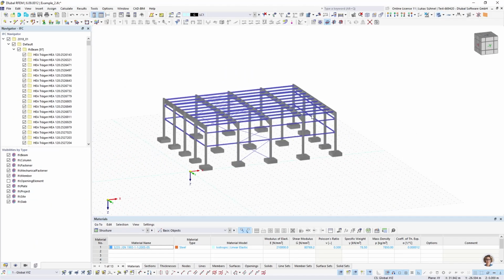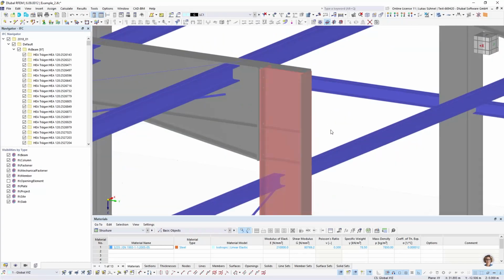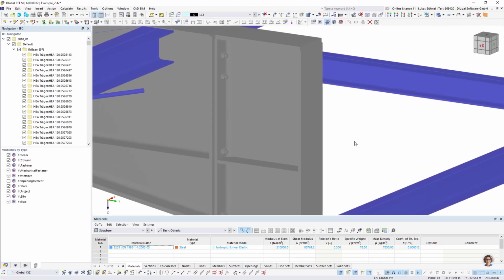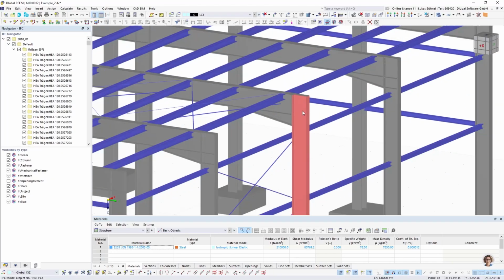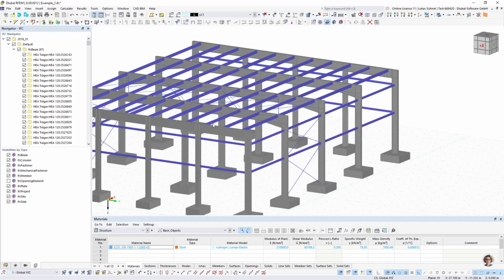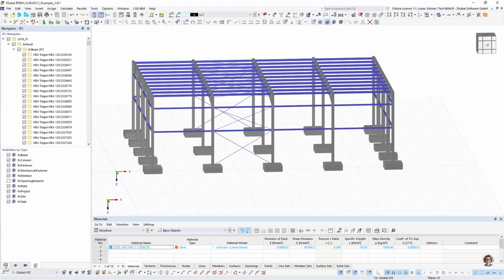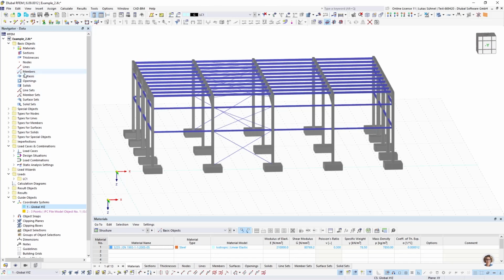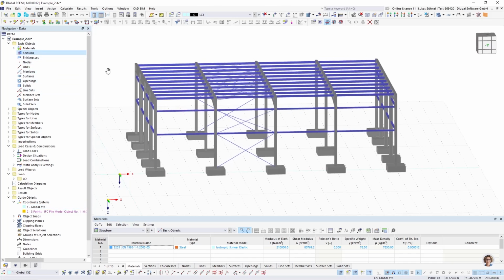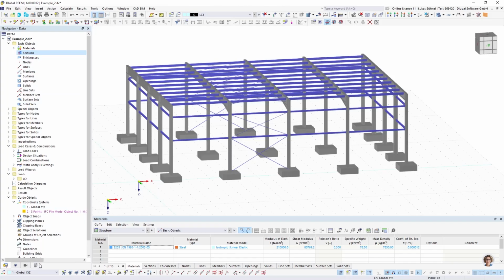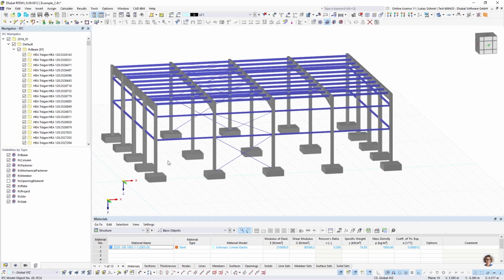Let's have a quick look. We can see the content of the IFC, similar to BIM Vision. So what we see here is our IFC objects. First of all, there are no native objects. So this is not a real member. There are no sections imported. This is just a graphical object. It's basically an IFC viewer.